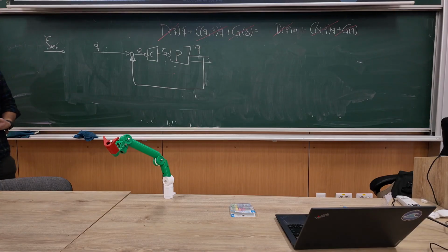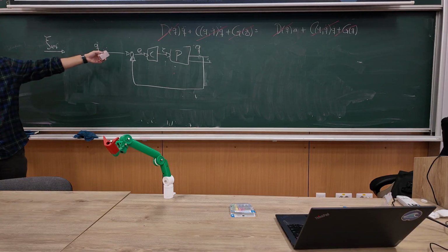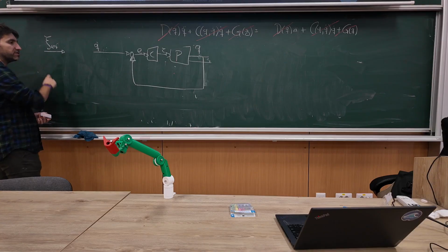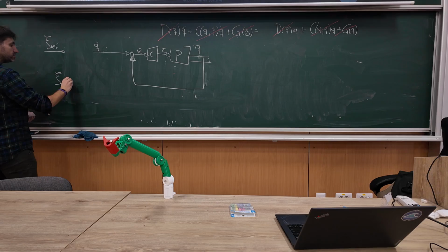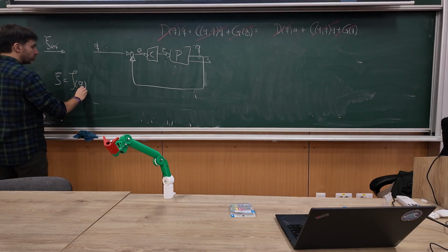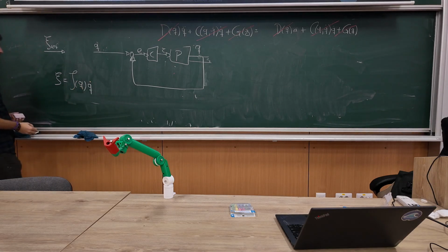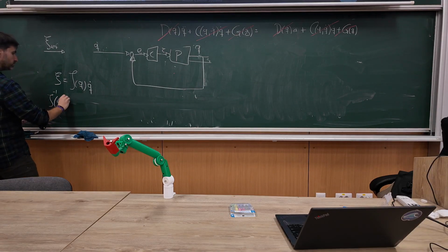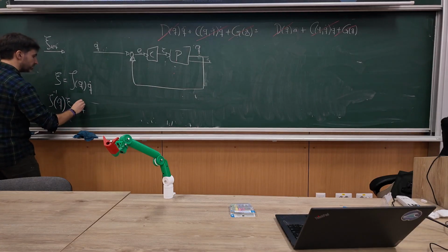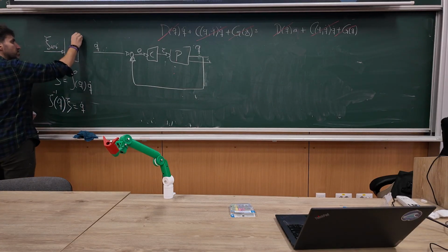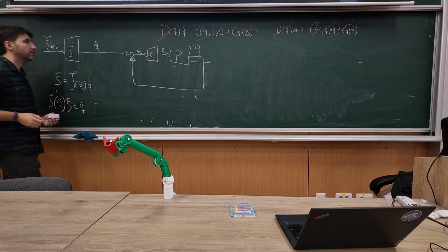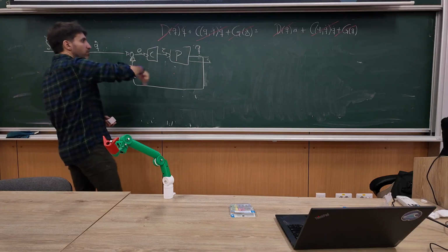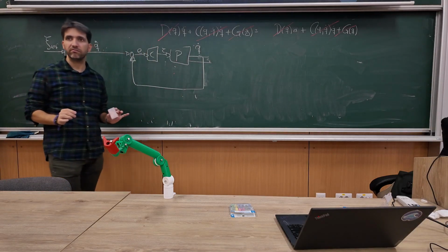positions or velocities. We saw we can do joint velocities, right? So how do I go from Xi reference to joint velocities? Right, so this is the Jacobian equation, right? If I take the inverse of the Jacobian, I calculate target velocities. So I take the inverse of the Jacobian, and this gives me joint velocities. And then I can do the control at the joint velocities level.